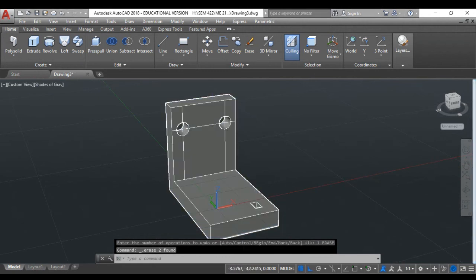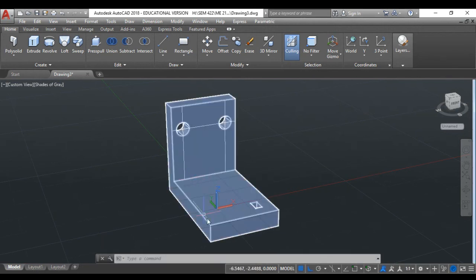Now, guys, let me take you back to the PowerPoint. How much is that thickness? 5, right? Okay. Now, how much is that width? 30. You see that width is 30. So the distance from this corner until I reach this line, how much is that distance, guys? Please tell me. You divide 30 by 2, you end up having 15 to the midpoint, right? And then you take 2.5 out of the 15, then you end up that this distance is how much, guys? 12.5. And this is the reason that I need that number to make it as offset distance.